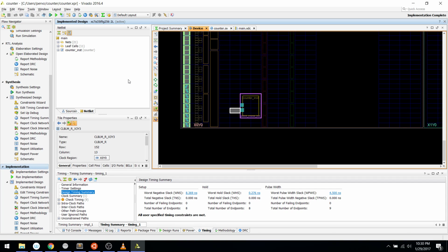All right. I'm not going to demonstrate XDC macros because I haven't prepared that, so I made too many mistakes. But anyway, XDC macros are a way you can organize a macro of modules, or cells you can instantiate, with a certain relative placement. You can then translate them around and have them snap to nearest relative to the constraints. So if you want to place something next to BRAM with an XDC macro, you can instantiate the macro, slide it around, and it will snap to nearest relative to the features it wants to be close to where you're trying to place it.